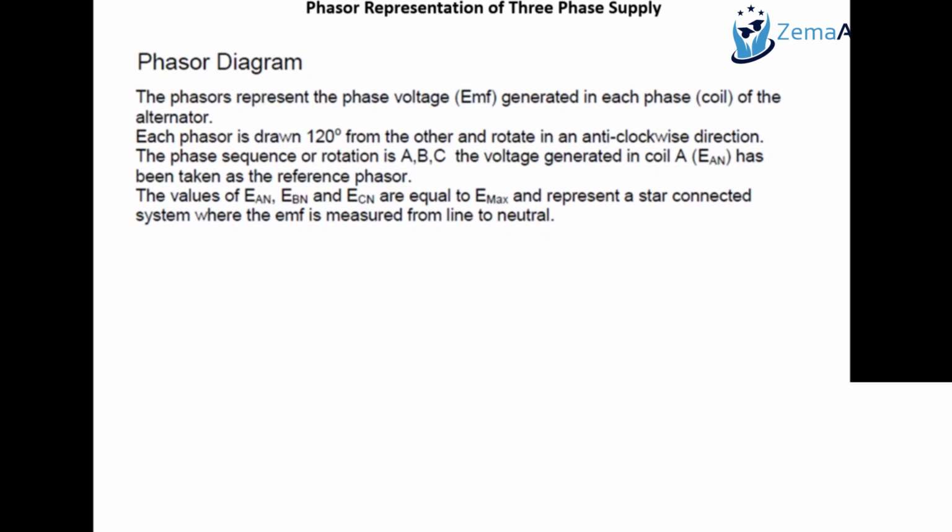It was all about to make sure when we do study the three-phase systems, we should know what the phasor diagram is, how we can draw phasor diagram more accurately. But make sure all three voltages must be 120 degree with respect to each other. That's the most important thing to notice.